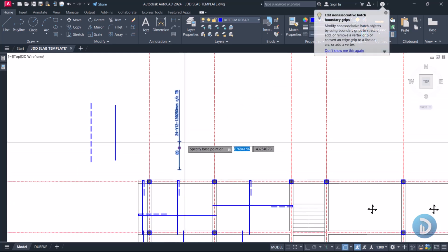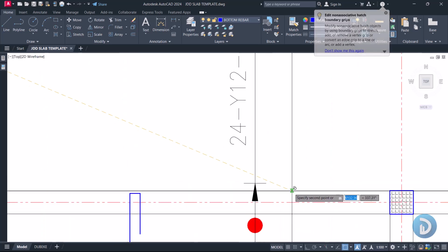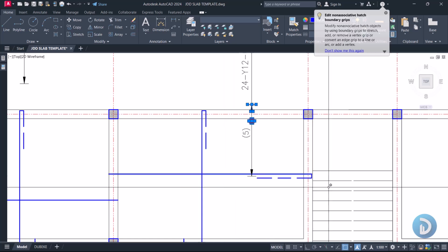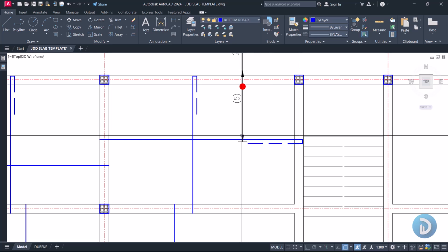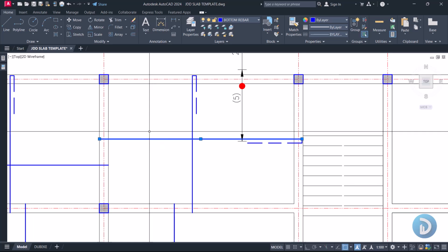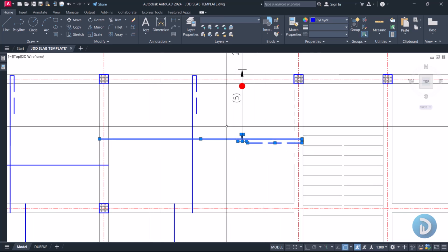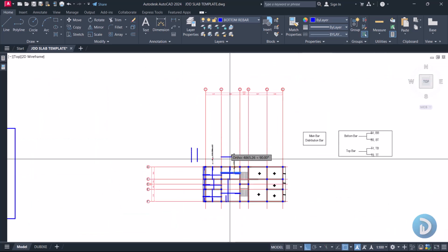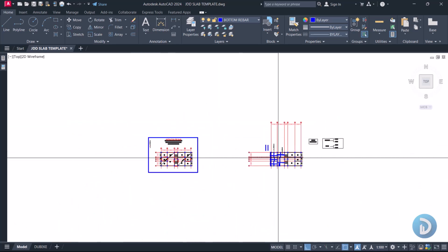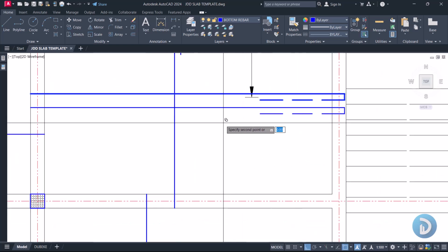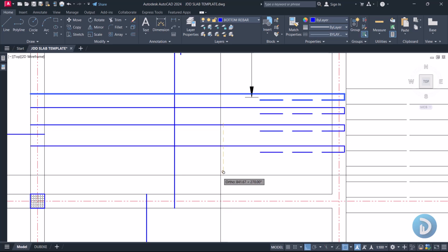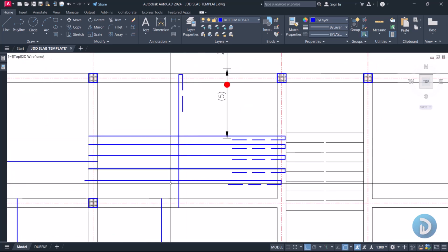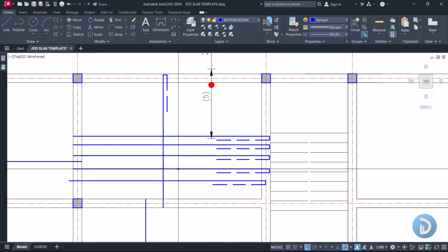and let's create another copy of this to somewhere here. Okay, then we can start with this very reinforcement on this axis. So we'll start with this. Then this reinforcement will run like this. We'll have one here because we are making use of our provided spacing, which is at 200 mm spacing. So this reinforcement will run here, and we'll have another one here after another 200 spacing, and another one here after another 200 spacing, and another one here after another 200 spacing. So what we are trying to do is to call out the number of reinforcement that will be required to construct this slab per panels.